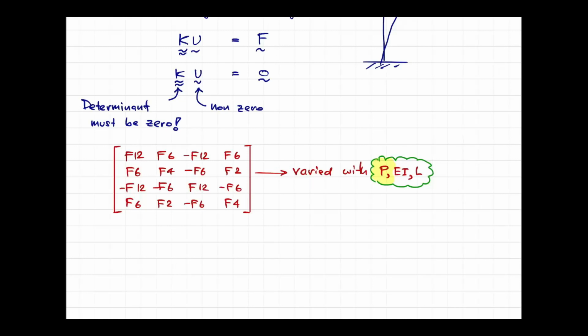Thus, the finite element approach or direct stiffness approach generally makes the structure stiffer than the reality. Sometimes if the approximate deformed shape can pick up the real deformed shape, the structure will be as stiff or as soft as the real structure.